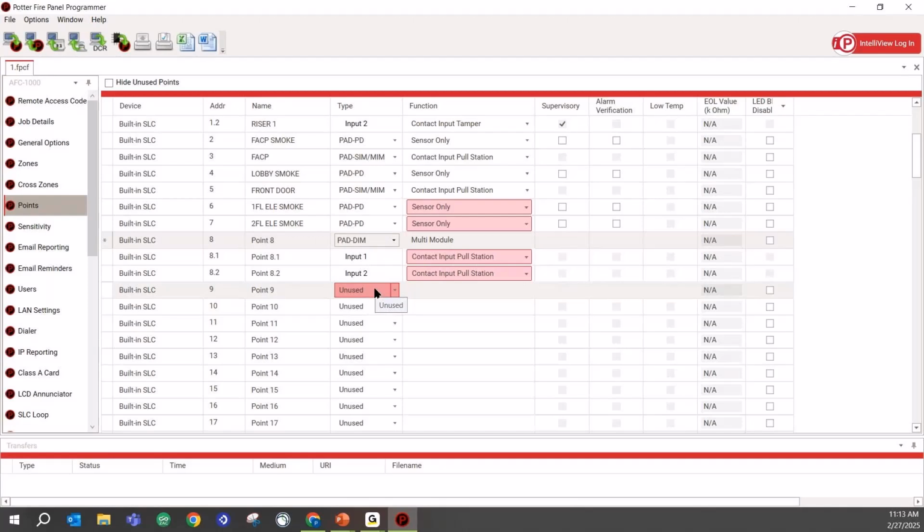Recently, ASME, or the American Society of Mechanical Engineers, said that they no longer want serviceable fire alarm devices in elevator shafts. The service response becomes much more complicated. You have to have an elevator technician out as well as your fire alarm technician. You have people riding on the top of cars. It can be pretty dangerous. So ASME said we don't want fire alarm devices that require direct service in the top of elevator shafts anymore.